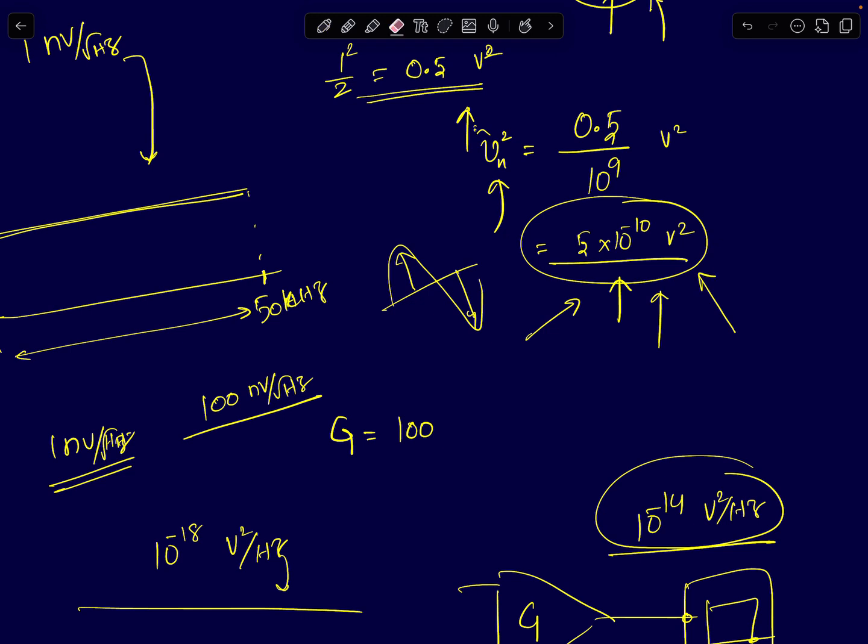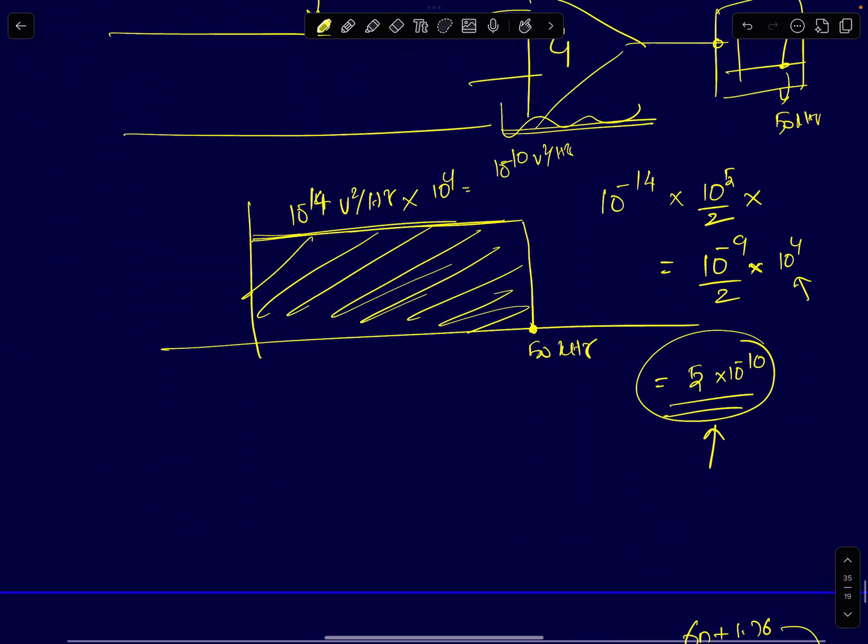If it is higher than the noise of the ADC, then you will degrade the SNR of the ADC further, right? You are adding a new source of noise. So your ADC's SNR will go down even more, which would then give rise to erroneous results. So if you want to pick an instrumentation amplifier that is driving a very high resolution ADC, naturally the instrumentation amplifier's input referred noise has to be very low. How low depends upon your system. I showed an example of a 90 dB SNR ADC and what should be the rough range of required input referred noise for that.